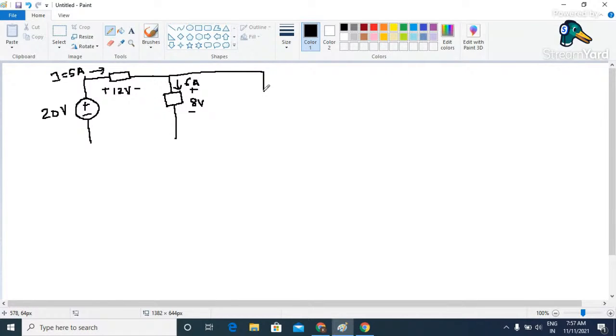And somewhere over here we have a diamond shaped structure. The moment we have a diamond shaped structure, it means it is going to be a dependent source. Then I have indicated an arrow, which means it is a current source, and the magnitude of this is 0.2 into I. Here 0.2 is a factor, and I indicates that it is a current controlled current source. Why is it a current source? Because it is a diamond with an arrow. The magnitude of this current source depends upon I, where I is the current flowing through this particular element, which is say element 1. So this is the example for a current controlled current source, and the circuit is closed like this.